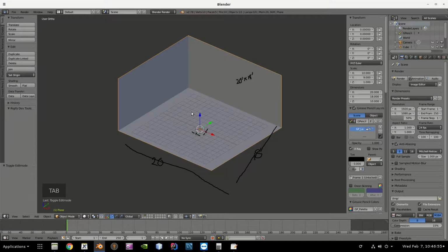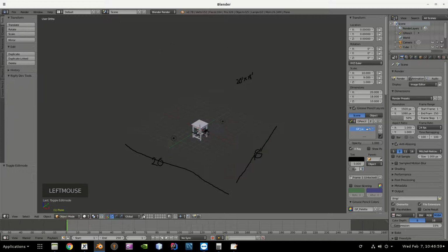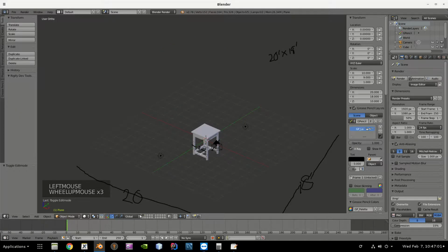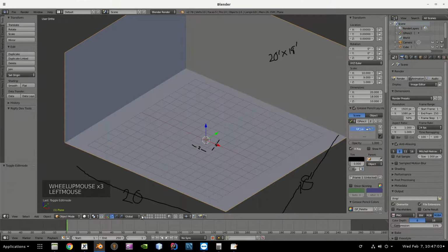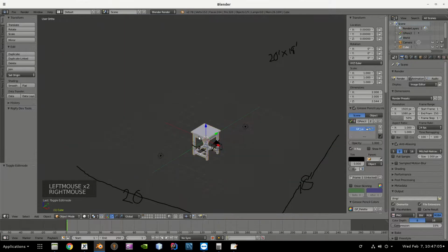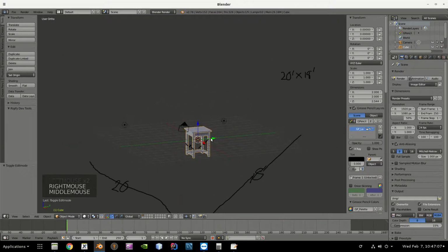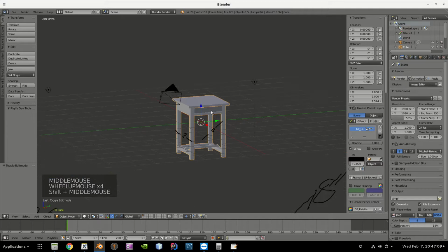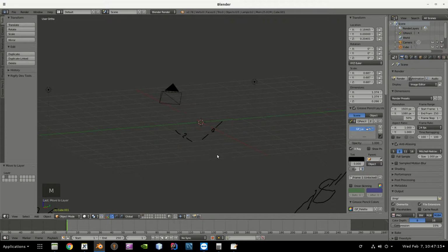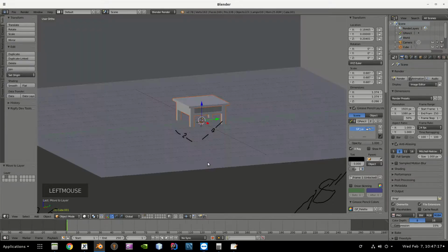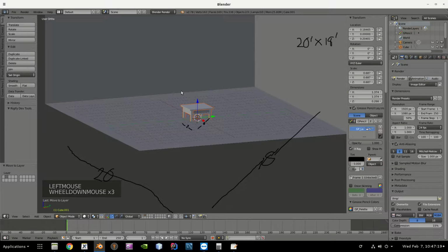Rather than doing so, let's say I build this room over here, I can go to the other tab. You can do that in object mode. So I can go over here and select this thing along with the drawer and hit M for move and move it to the final layer where I am composing this scene. See, it's not placed in the right spot, but now I can place that.